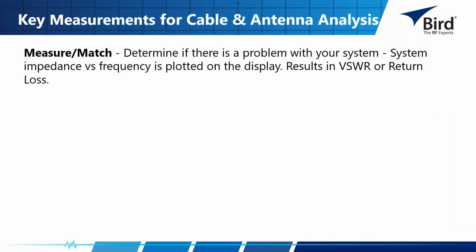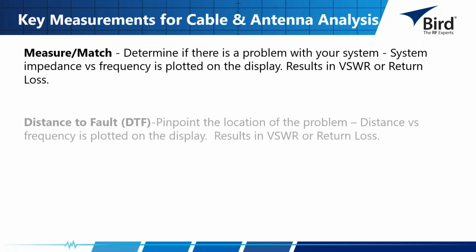The key measurements that we'll discuss today are measure match, and this is a measurement to determine if there is a problem with your system. System impedance versus frequency is plotted on the display. You get your results back in VSWR or return loss.